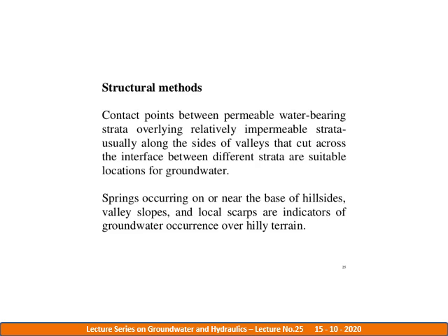Foremost and very important, the geophysical survey will give an estimate of thickness of the various subsurface layers. Information can also be obtained regarding the aquifer material, anisotropy and the degree of fracturing. However, additional investigation like well drilling and logging will be required for the final assessment.